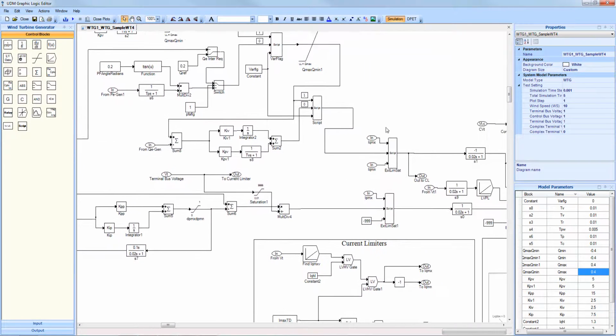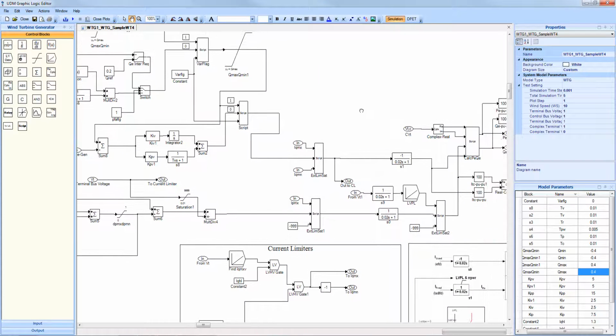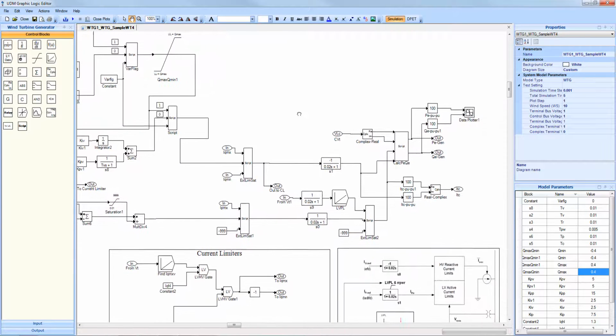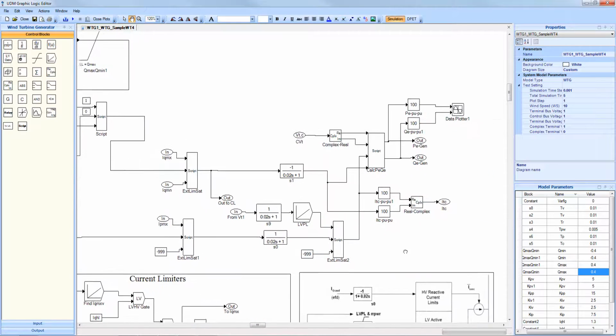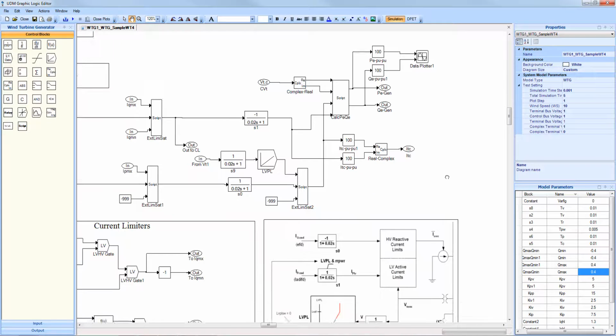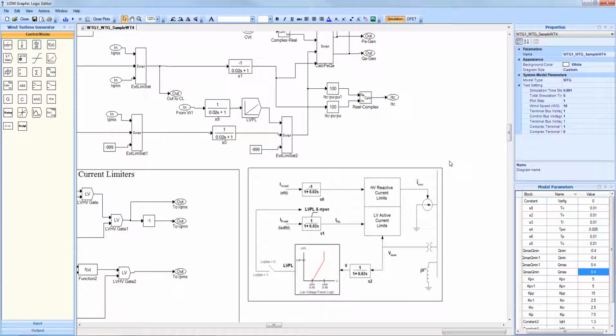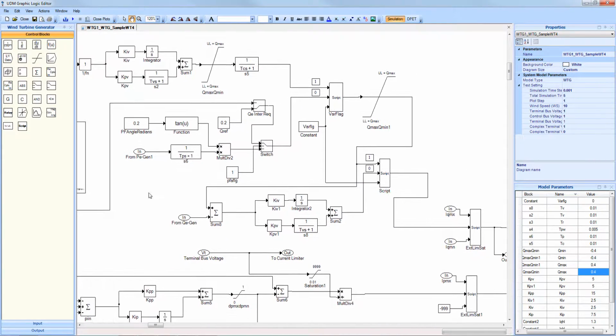It also uses the go-to blocks in internal mode of operation as well as external mode of operation, and it also utilizes the new current injection inputs for the voltage and current injection outputs for the terminal current of the wind turbine generator to allow it to simulate current injection simulations required by different interconnection standards and models. That gives you a high-level picture of the wind turbine model.